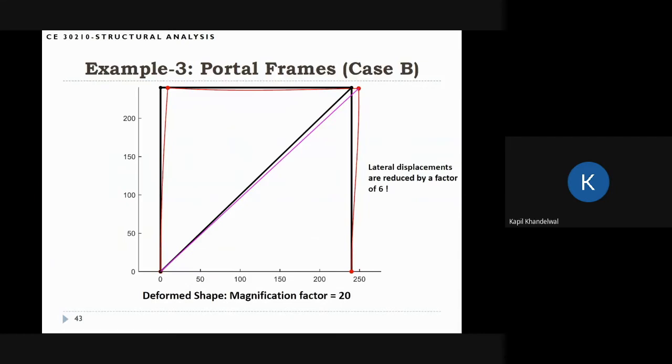And bracings are very important members because they can actually provide lateral stiffness to a frame. So if you want to reduce lateral motions in a frame, you can put bracings. And actually, when you learn about structural systems in your future classes, or if you happen to take a class on structural systems, they talk about different kinds of bracings that can be used, and there are different patterns of using bracings and so on and so forth.